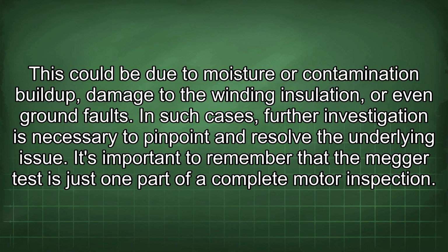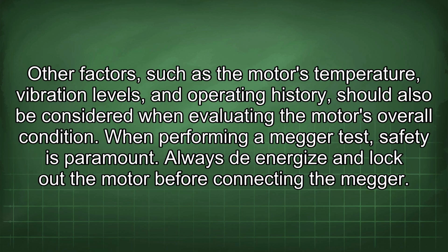It's important to remember that the Megger test is just one part of a complete motor inspection. Other factors, such as the motor's temperature, vibration levels, and operating history, should also be considered when evaluating the motor's overall condition. When performing a Megger test, safety is paramount.